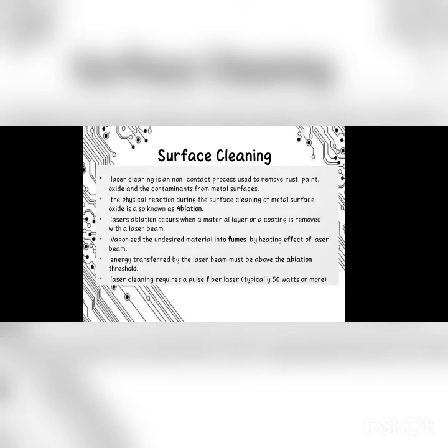Laser ablation occurs when a material layer or coating is removed with the laser beam. It vaporizes the undesired material into fumes by heating with the laser beam. The energy transferred by the laser beam must be above the ablation threshold. Laser cleaning requires a pulsed fiber laser, typically 500 watts or more.